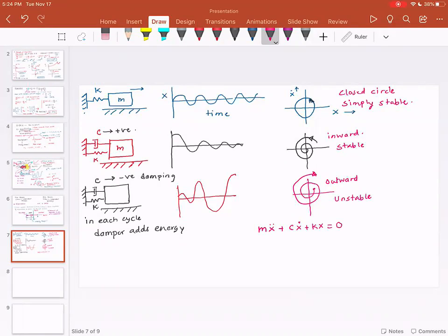Now I want to write this expression in the state space form. So step 1, when we do the state space, is to find the variable that does not have any derivative, no dots. So this is my first variable. This is my second variable. Now why do I need two variables? Because please note, the highest order of derivative here is 2. That's why I need two variables.